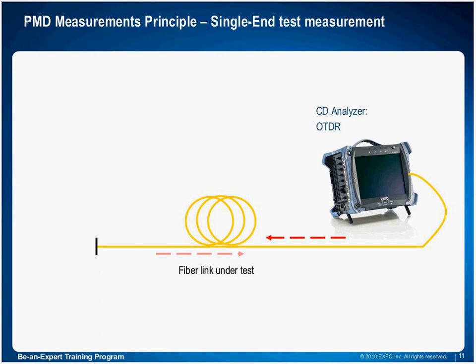It's not available on the spec sheets, but I'd estimate that anywhere between 100 and 200 meters of standard single-mode telecom fiber would be the shortest link at which you would want to measure. However, I must repeat that this is a very, very short length. At this length, chromatic dispersion is typically not even a factor.